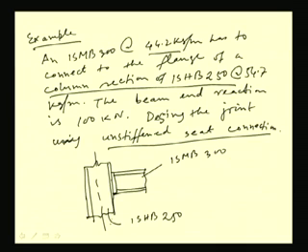This is beam and this is column, and we have to find out the dimensions of the seat angle and the cleat angle, and the joint, means what will be the number of rivets required to connect this joint, what will be the size and thickness of the seat angle, and other details. How many rows of rivets will be required, what is the total number of rivets, what is the diameter of rivets, all these things we have to find out.